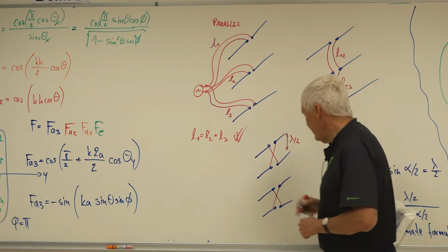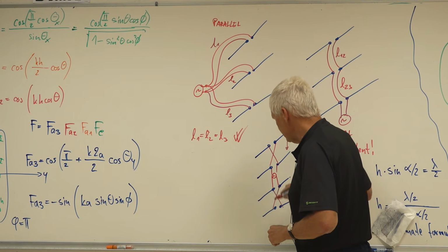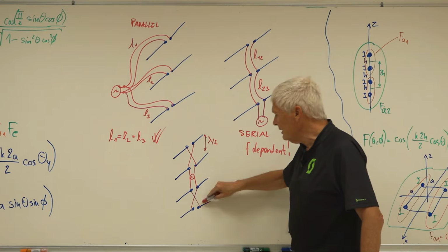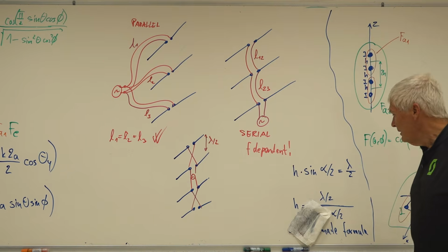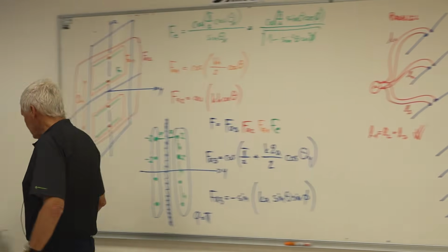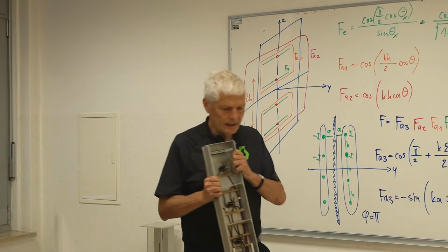long. And I simply connect the generator here in parallel to both groups. And this was a typical solution for television antenna. So combined serial fed and parallel fed. So all this can be done, and all this you can see on the samples. Say like this one here, this antenna is parallel fed.